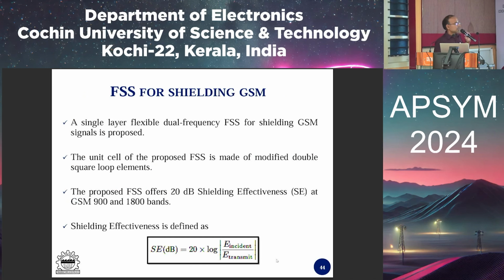Then suppose we think of shielding the GSM signal within this auditorium, we may go for jammers or we can go for some kind of absorbers. So this we proposed: we can go for this FSS based on paper material as well as some copper strips, okay, without disturbing the ambience as well as the aesthetic nature of the hall. We can bring in some kind of shielding.